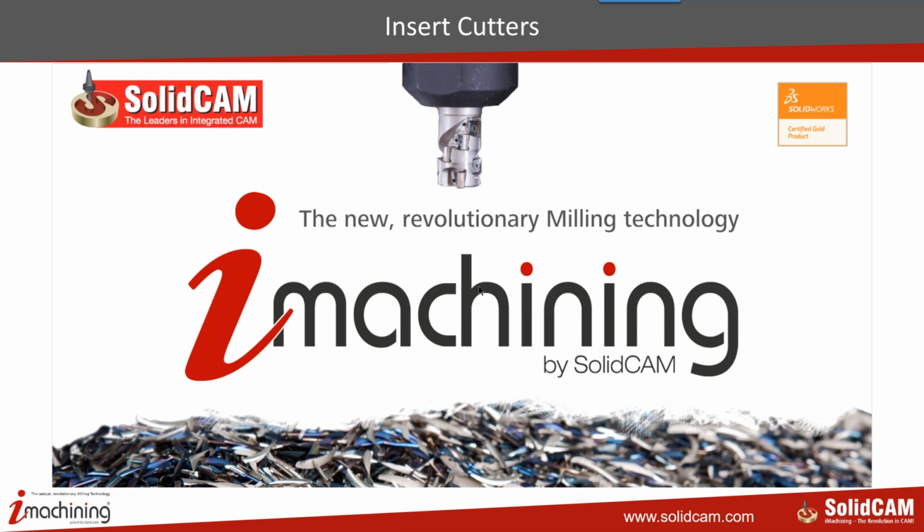Generally, insert cutters, especially indexable porcupine insert cutters, when used with good cutting conditions, remove material faster than solid carbide end mills and exhibit tool life or insert life comparable with that of solid carbide end mills.